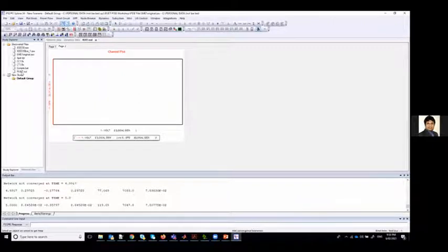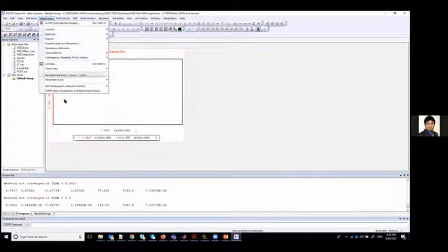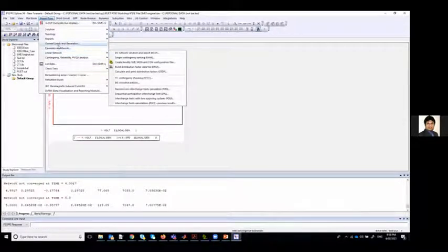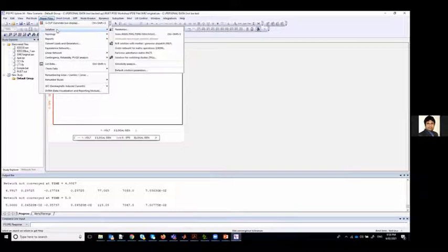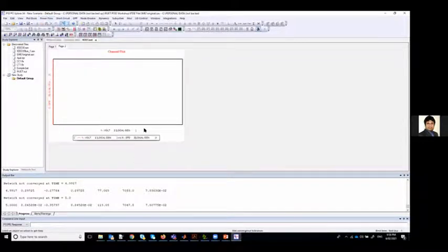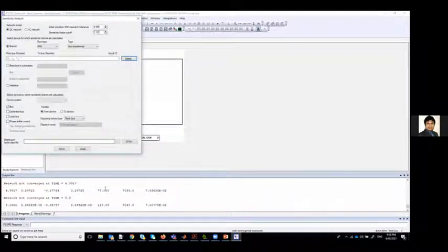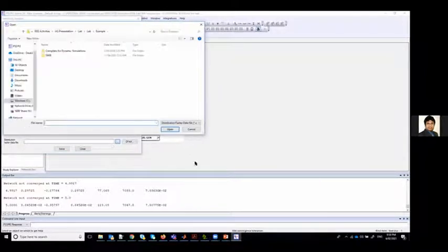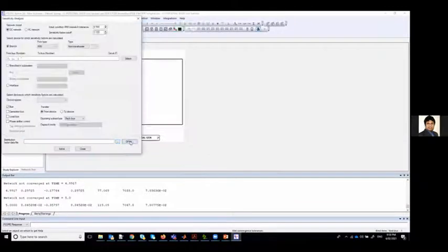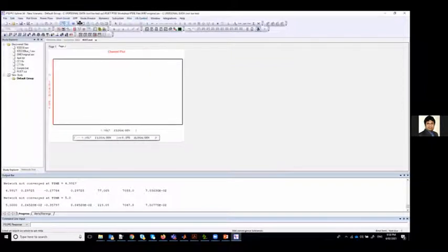So this is the dynamic simulation, but you can do a lot of different things. If you just click on this, okay, linear network analysis, equivalent network, and you can do sensitivity analysis. You can do sensitivity analysis, one bus, let's say bus 3. I just covered some part of it, okay? With respect to some data, you can do the sensitivity analysis, okay? So you can do many different things with this software. It's not only just the simulation, and you can have a subsystem.